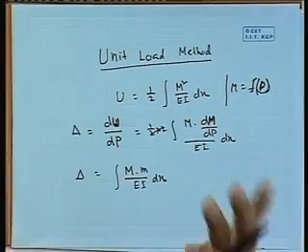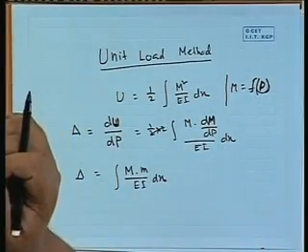So, we came to a much more systematic form of the energy method. What we have to do? We have to take the structure and write the expression for the bending moment for the different zones due to the load, that is capital M. And what is small m?